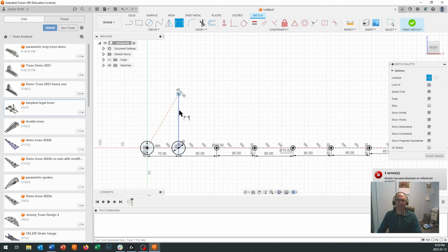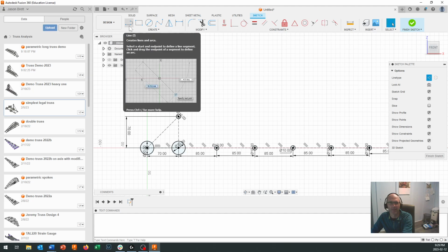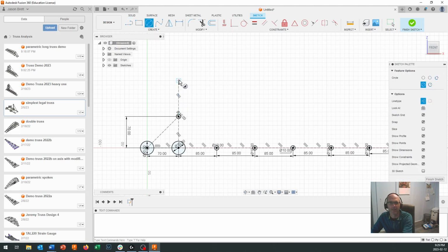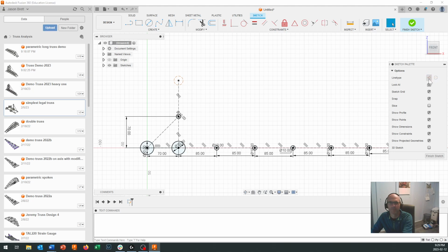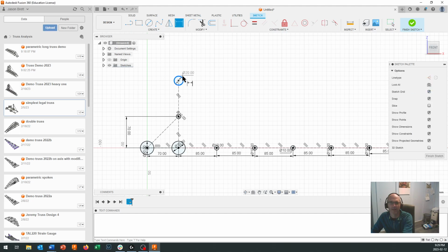What I actually wanted to dimension was this line right here, and I've got that set at 120. You know what? That strikes me as a little bit high. I think rather than have that be all that tall, I'm just going to make that into a 70 millimeter high piece. And then from there, I am going to create another piece that comes up here and create a node right up here. And that node will be, pick that. Sorry, I need to pick that. I need to turn off its construction. And now I can come along, and because I didn't put a dimension on that earlier, I can dimension it and make it 10.